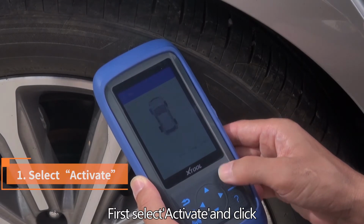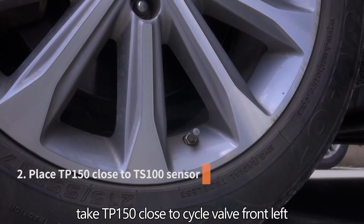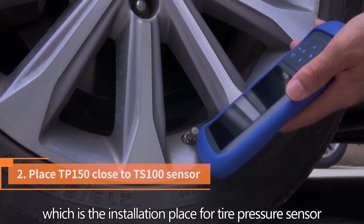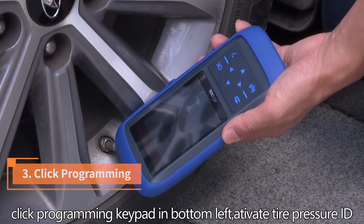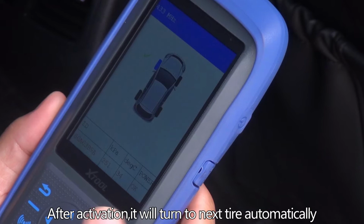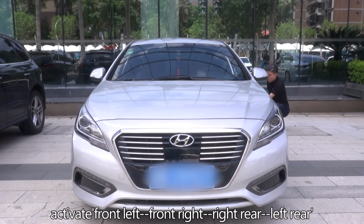First, select Activate and click. The vehicle model image displays blue to represent the sensor which needs activation. Take TP150 close to the front left valve, which is the installation place for the tire pressure sensor. Click the Programming keypad in the bottom left to activate the tire pressure ID. The vehicle model image has a corresponding response. After activation, it will turn to the next tire automatically. Activate front left, front right, right rear, left rear.